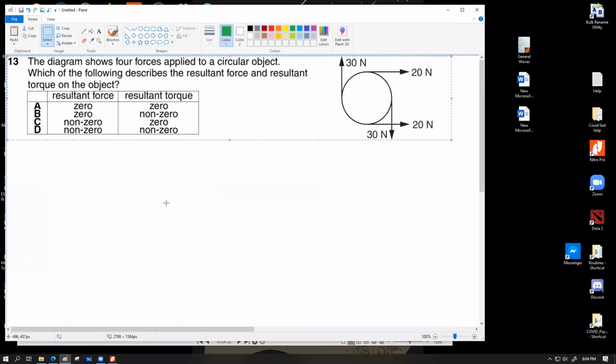What I need you to understand is that the resultant force would be 0 if you have equal and opposite forces on the object. One of the easier ways to observe this is to consider the sum of the forces along two axes, the vertical axis and the horizontal axis. If the object is in equilibrium along both the y-axis and the x-axis, then we can say the resultant force is 0. The other thing is that for moment, some rigorous calculation is needed.